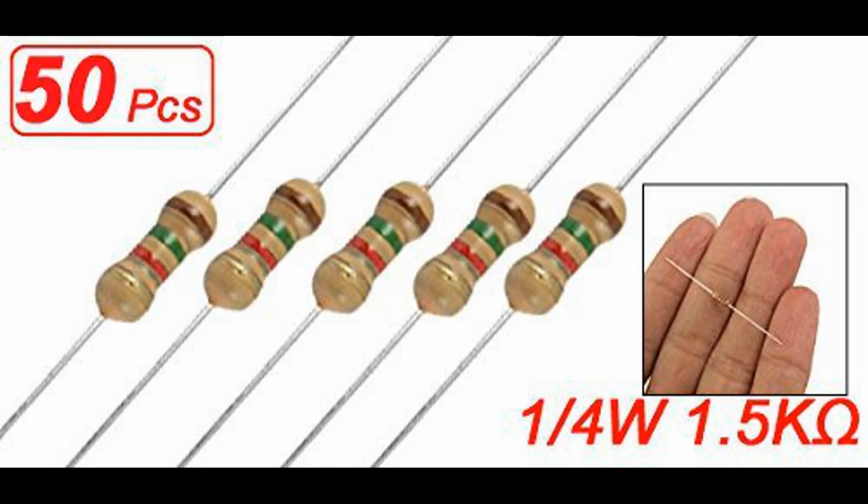The temperature coefficient of a resistor is a measure of how its electrical resistance changes with variations in temperature. It quantifies the rate of change of resistance per degree Celsius (°C), or per degree Fahrenheit (°F), and is an important characteristic to consider when selecting a resistor for temperature-sensitive applications. The temperature coefficient is typically expressed in parts per million per degree Celsius, ppm/°C, or parts per million per degree Fahrenheit, ppm/°F. Here's a more detailed explanation of the temperature coefficient.